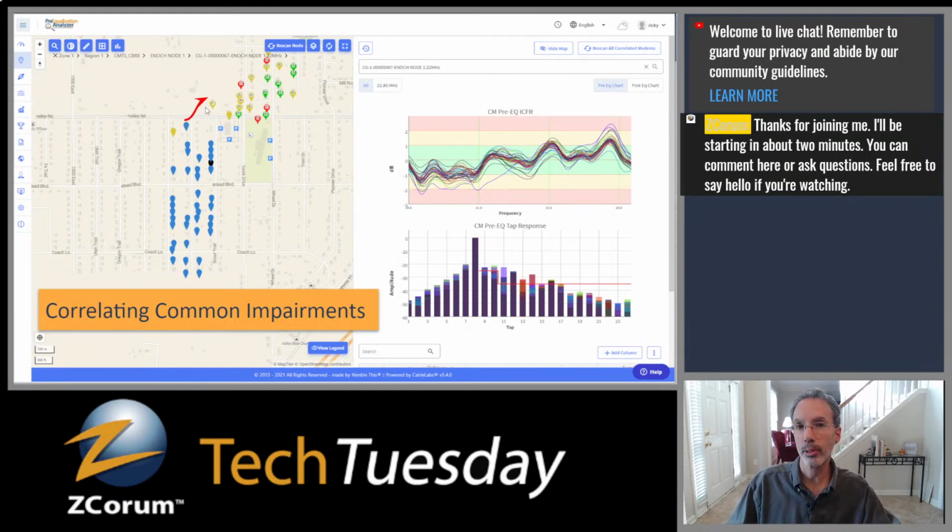It could be a crack in a cable where some water's gotten in. It could be an active or a passive here with a bad connector. Could be a tap or something that's got a problem in it. But in this case, all of these devices would be going through the same path. So for all of these devices, they have the same echo cavity to deal with, right? Other than other things going on with those devices, like maybe an in-home problem, they're all having to pass through this particular path here. So they're all going to have that same outside plant echo cavity. So that's the distance you're looking for.